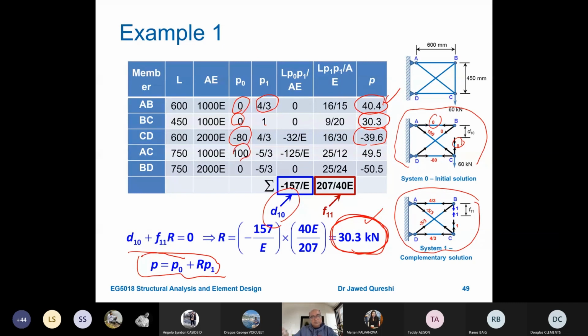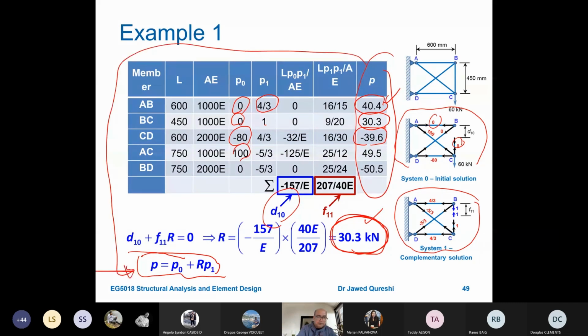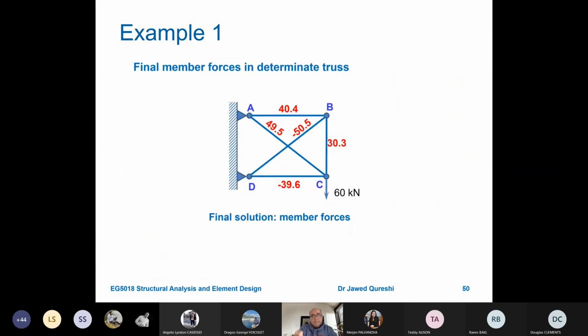Again, repeat the same process for all the loads. This is coming from this formula. And in the same way, you simply bring these values on the diagram itself. Now, this is telling you that, okay, tension is happening here. Our sign was fine. Now, compression is happening in member DC. Tension is happening in this member AC. And then we get the member forces.